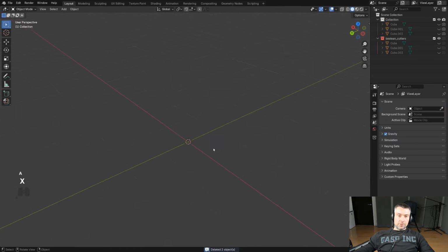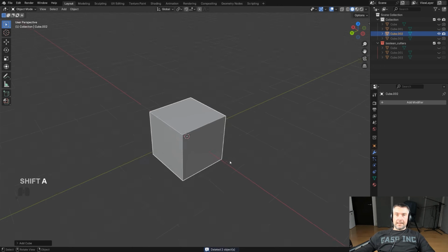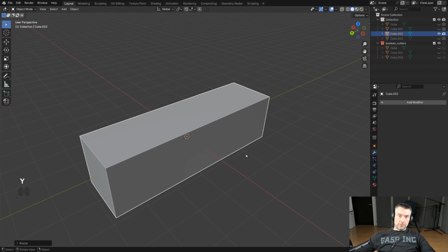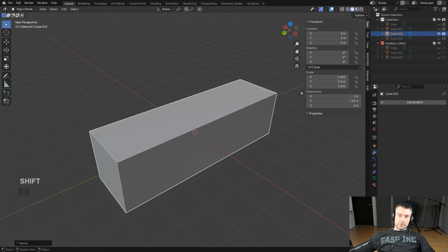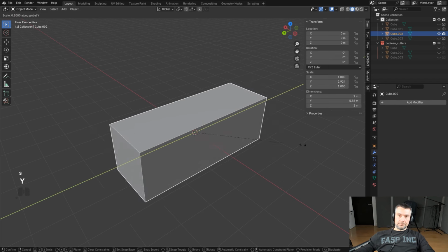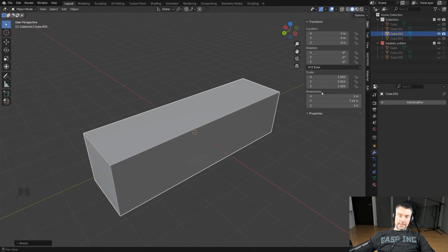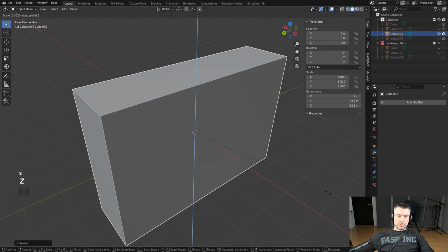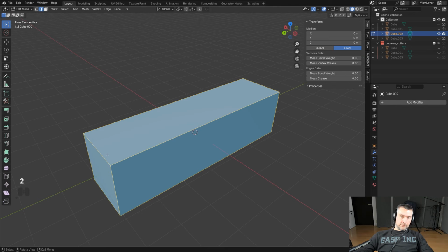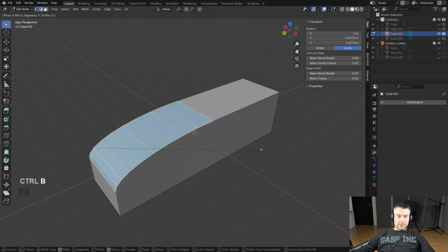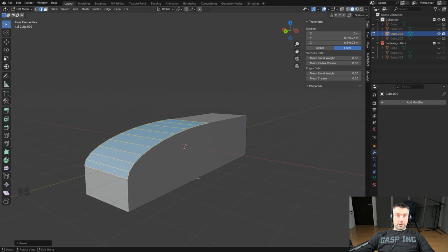The last issue I'm gonna show you with bevels, I think, is gonna be scale problem. So when you change size of something in object mode, not in edit mode, if you go to N panel, you'll see that under item, your scale is going to be different on the y-axis than on the x and z, because we haven't scaled on x or z, we scaled on y, so it gets stretched. And when you're gonna be adding bevels to this mesh like this, Control B, you'll see it's gonna go really weird. Unless this is what you're going for, that's not really how bevels should run.